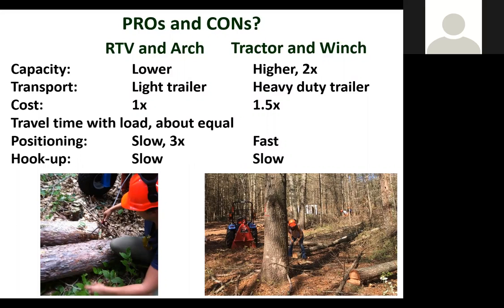But the positioning and the hookup for the RTV is much slower. It took on average about 3 times as long to get hitched up with the RTV and arch than it was with the tractor. With the tractor, you set the tractor, you put on your choker chains, you run your cable out there, and boom, you zip it into place. Whereas there's an awful lot of positioning that needs to be done with the RTV and the arch. Very effective once it's in place, but it's a little fussier to do.